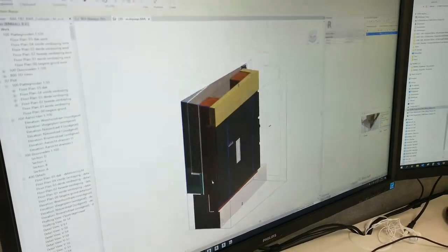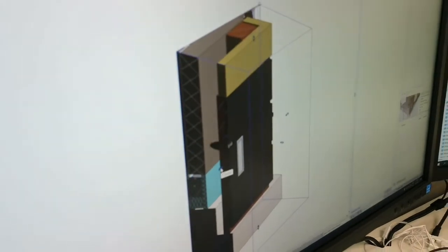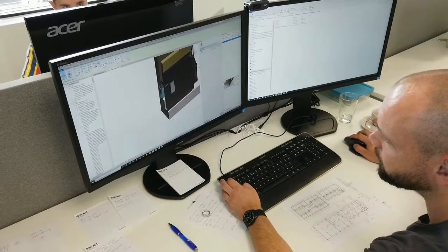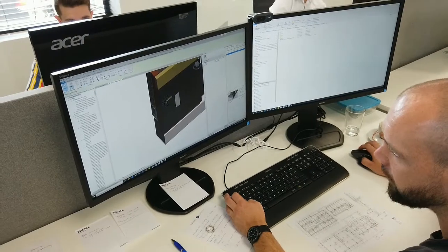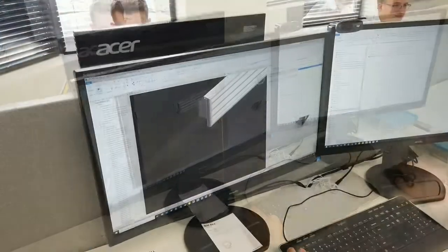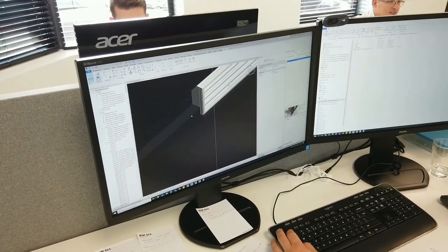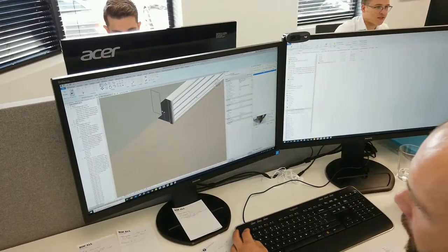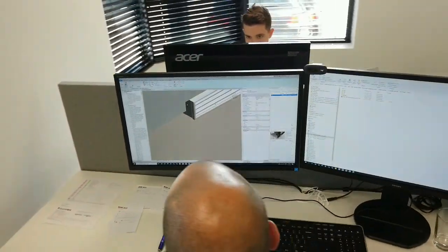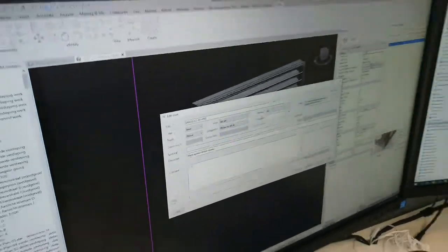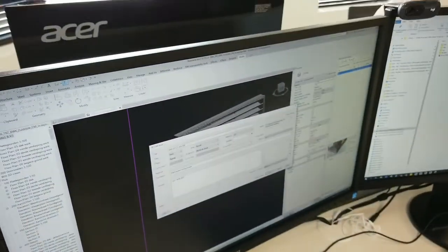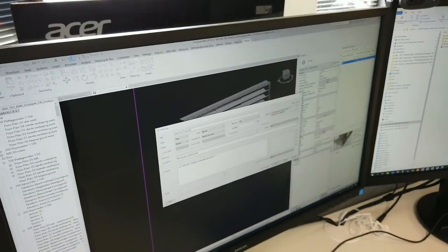What you are seeing here is my colleague using Revit with the BCF Manager add-in, the free add-in. He collected the issue from an online BCF server, and he knows what to do with the issue, how to solve the problem. After that, he will resolve the issue and send it back to the BIM coordinator to communicate, hey, this issue has been resolved.